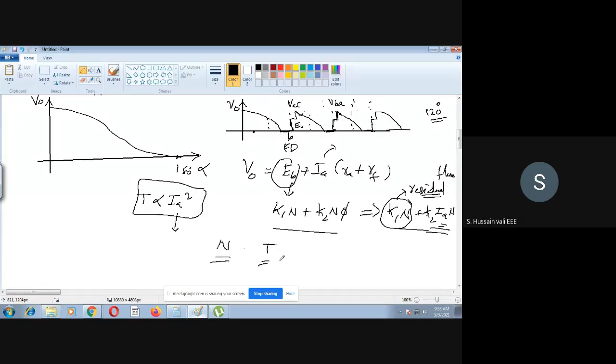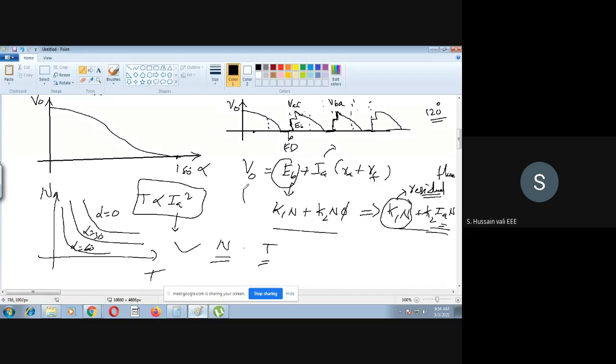So what is the relationship you will get? I will tell you one important thing that I told you already, that the speed torque characteristics of your DC series motor is always like this, whether it is single phase converter or whether it is three phase converter. Okay, this you will find out because this is a non-linear shape you will get. So as you go on increasing the value of alpha, you will get this thing, that this is the speed and this is the torque. This relationship you will get if you simplify all these equations. Okay, this we have done already in the previous cases where you find out the series. There you can extract and you can get it here also. Okay, there is no other thing here.